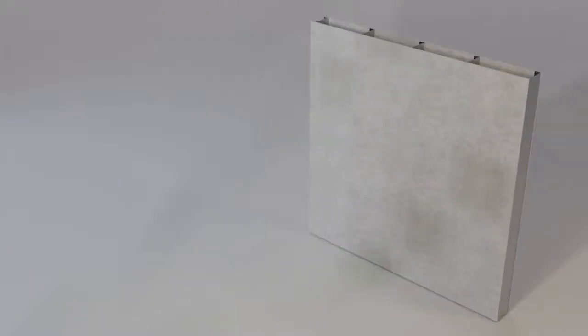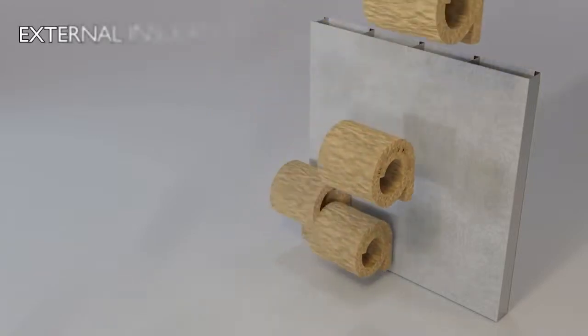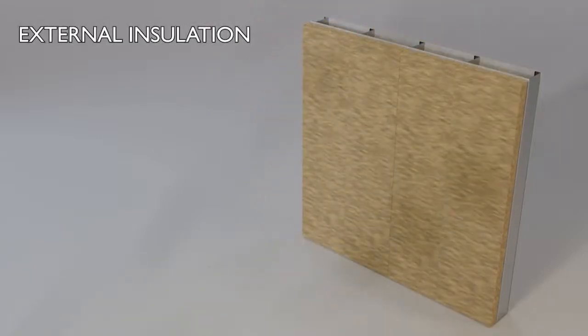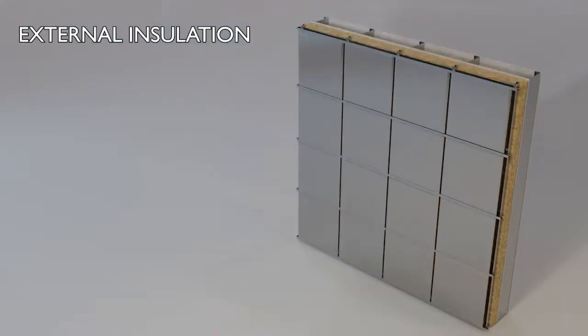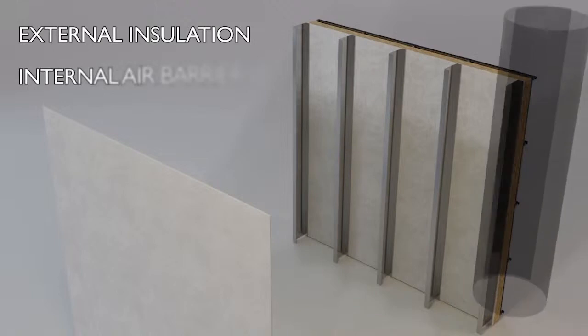The final type of wall we'll consider is facade walls. While certainly less common in refurbishment projects than the other walls we've discussed, change of use or recladding projects may require consequential upgrades to thermal performance. In a typical steel frame facade wall, the bulk of the insulation is normally placed outside of the sheathing, which is typically of cement fiberboard or similar.